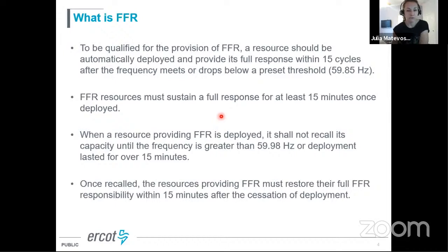Resources must sustain full response for at least 15 minutes once they're deployed. And they should not recall their response until frequency is greater than 59.85 Hertz, or deployment lasted for over 15 minutes. So this is the recovery frequency or 15 minutes, whichever is faster.